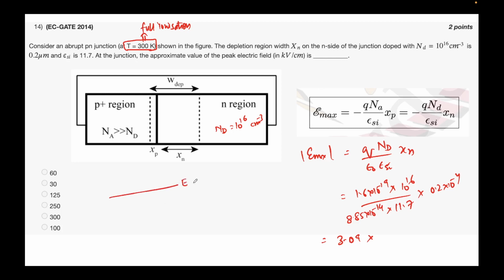So let's talk only about the n-type doping here. This is EC, this is EV. There is something called the dopant level, which we denote as ED. Assume it's a silicon semiconductor, so this is your EG of 1.1. Let's say you are doping it with a lot of phosphorus. At 0 Kelvin, this is how the picture will look.